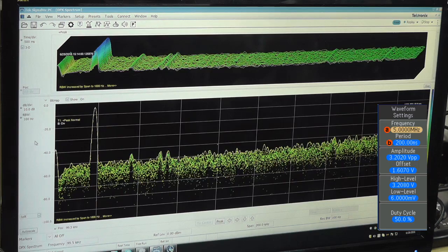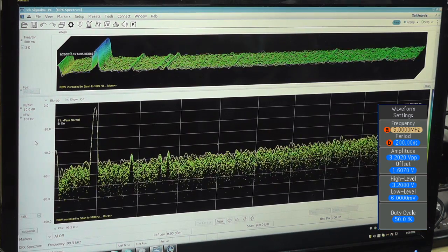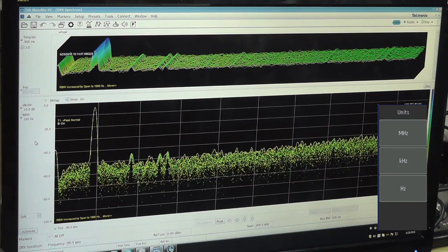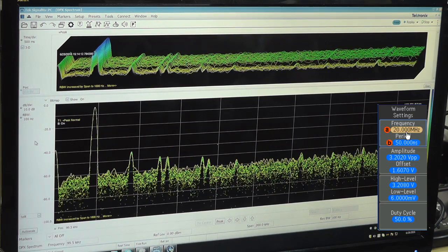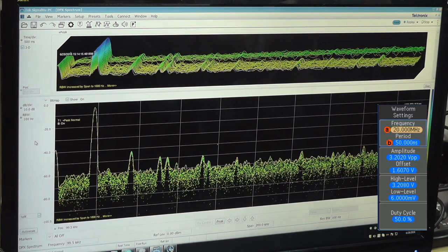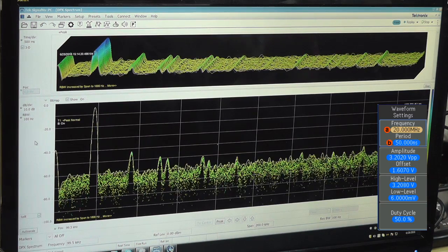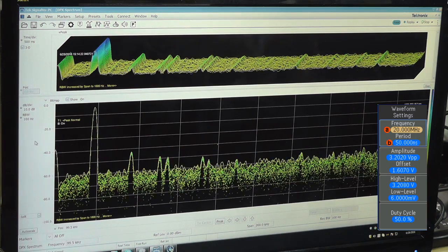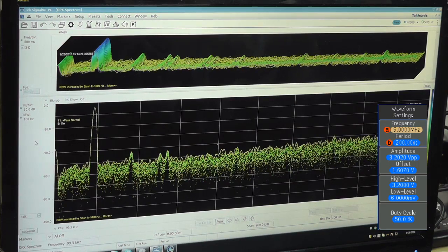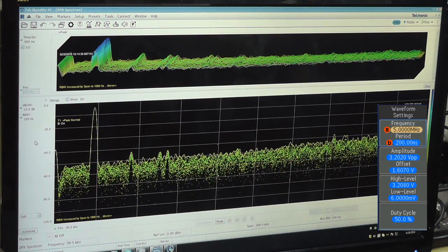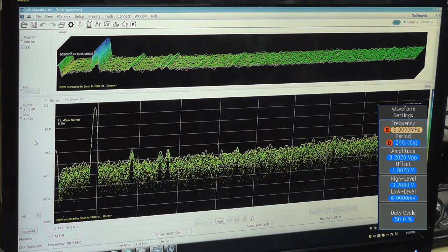So let's go ahead and change our sample frequency, which is currently 5 megahertz, as you can see here. If we change it to 20 megahertz, now watch the screen, watch the noise baseline. Boom, down it goes. Matter of fact, it uncovered some noise. Good for us. But right there it is. It actually works. We did it by a factor of 4 and dropped our noise. We'll take it back to 5 megahertz. And the noise floor will come up on us. You'll see we have a lot less room between the top and our noise now. So oversampling works. This is cool.